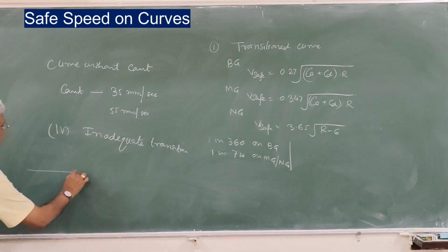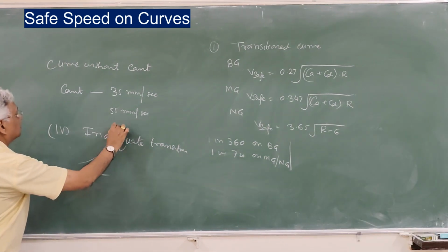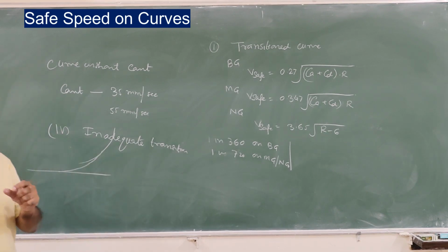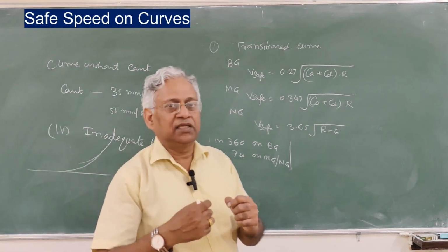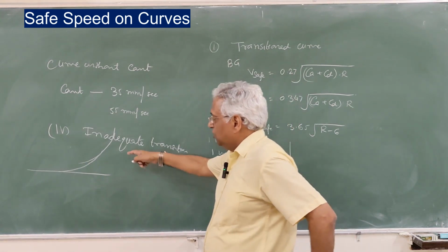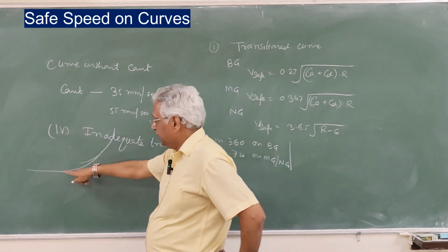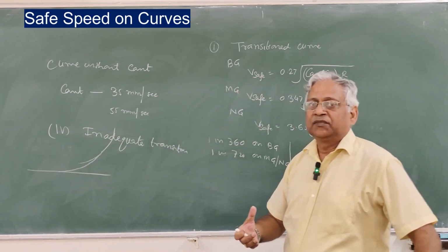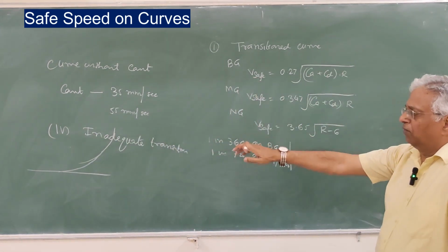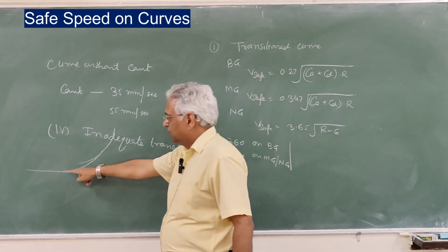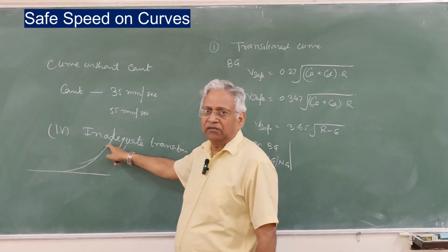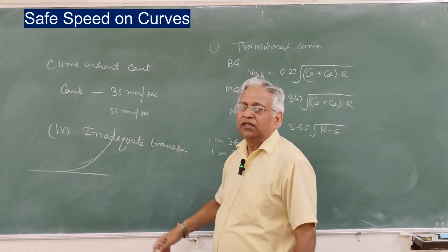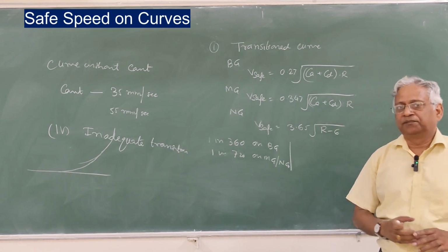In this case, with a circular curve and a transition curve, the rate of change of cant deficiency should be such that the overall speed on the transition and circular curve is optimized, almost uniform from when it takes off from the tangent till it reaches the circular curve. The average speed on the transition and the average speed on the circular curve are almost the same.